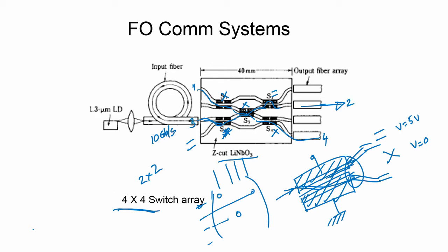We will assume that the signal is modulated in whatever format you wish. Typically, as you know, the waveguide widths are of the order of 4 microns, with about 2.5 microns depth, and the electrode voltage is of the order of a few volts, and the overall chip would come to 40 millimeters.